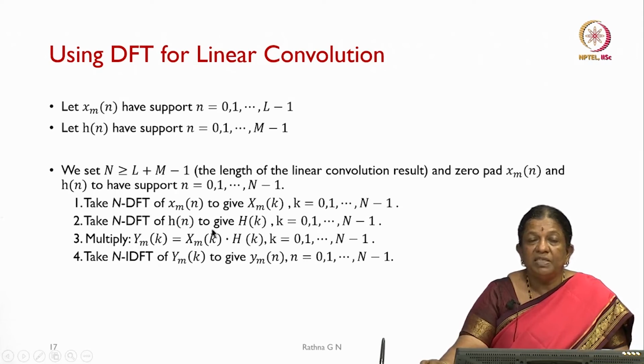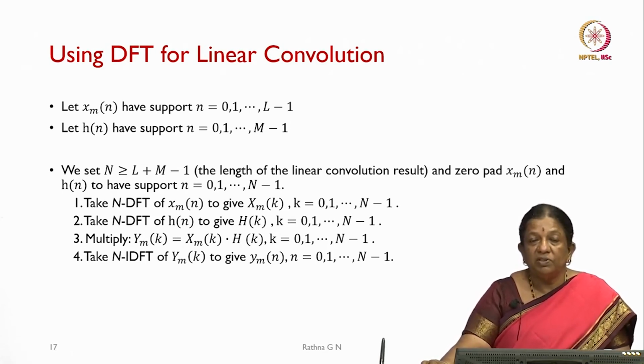Although we are doing this three times, since two N-point DFTs and the N-point IDFT cost the same, with a complex multiplication in between, our computation time is still better than the direct computation, and the result is equivalent to our linear convolution.